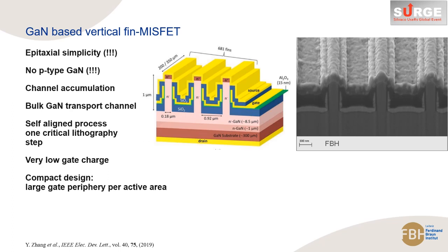The fin MOSFET concept has many advantages. The fin MOSFET has simplified N-type GaN epitaxial layers, and no P-type layers are required. In on-state, the channel transport is based on electron accumulation, and fin MOSFETs enable a very compact design with very large gate periphery per active area.